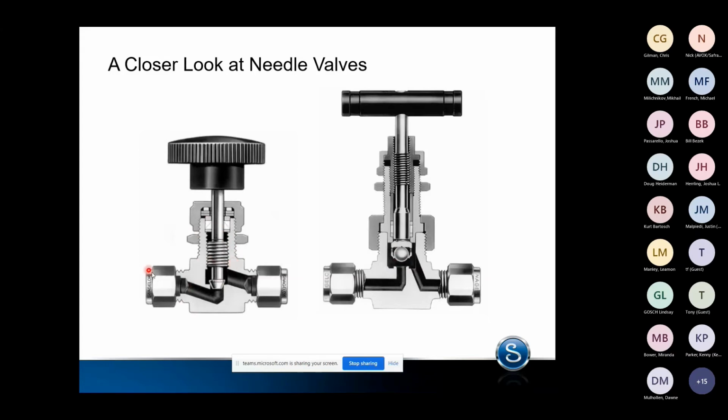When we do that, one of the challenges with this valve is that this stem thread is lubricated and there is no seal between those threads and your system. So depending what your media is that's running through it, those stem threads are wetted, and that lubricant, which is not globbed on there, but over time can get washed out and actually contaminate or get into your process media.